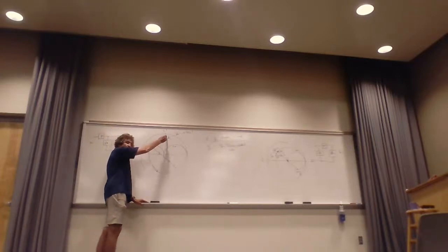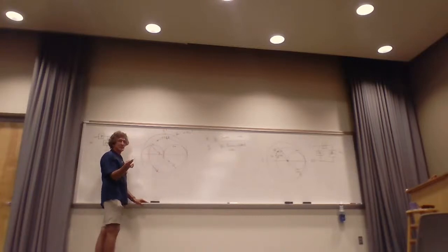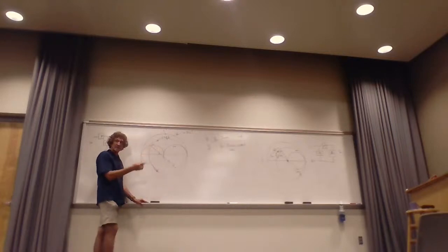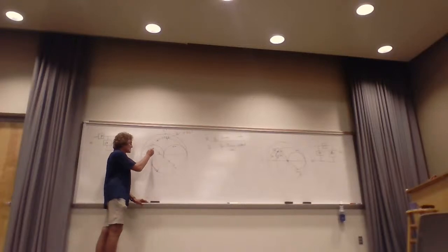Here, your impedance. That's where I came in. 1 over that's admittance. Now I'm going to add in parallel, not series, because it's an admittance. So I'm going to add in parallel, or shunt, admittance till I get to this point, or I could get up here, either one. I could go here or here, either one of those, but I need to add an admittance, a positive j, which is a capacitor, but it's in parallel. So I can get to this point or this point.